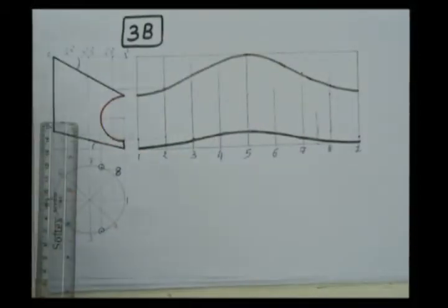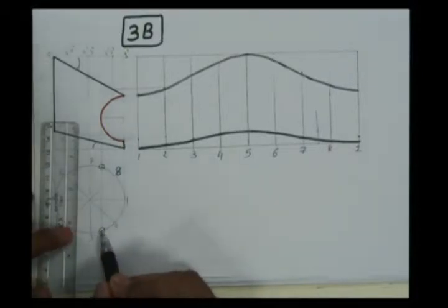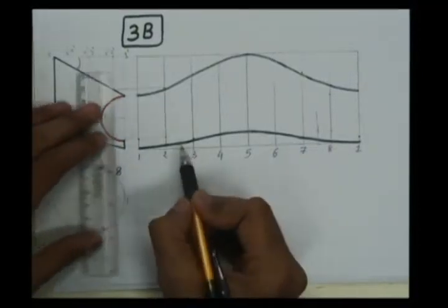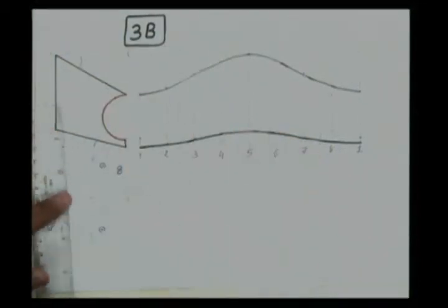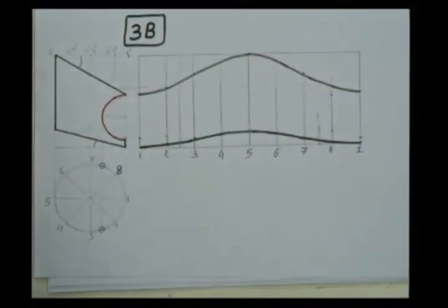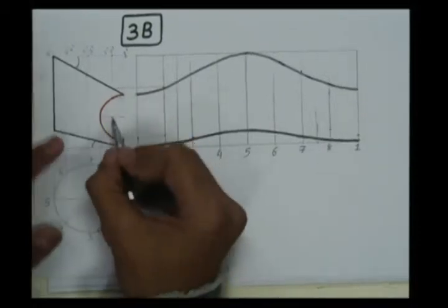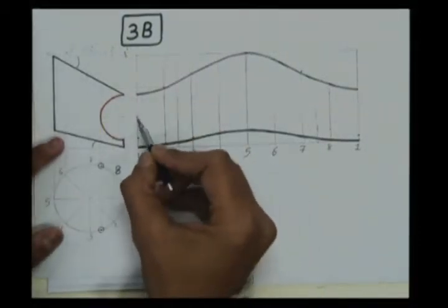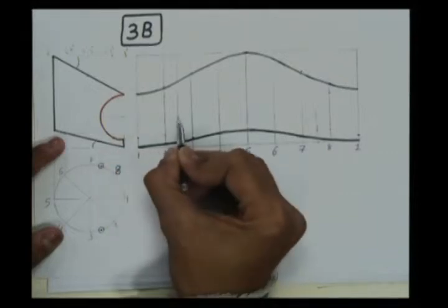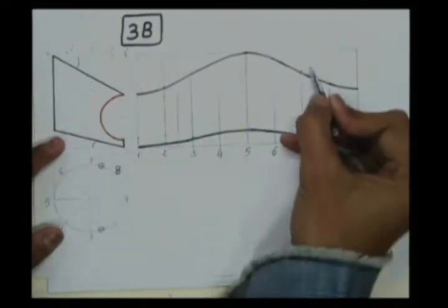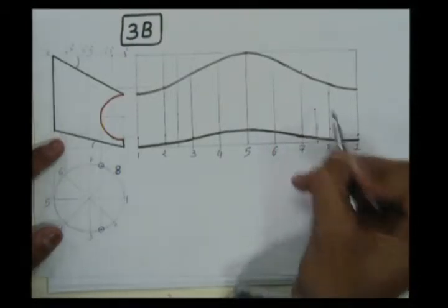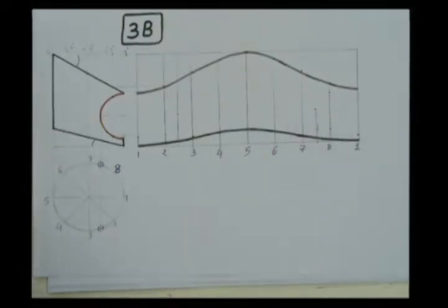Similarly from point 2, between 2 and 3, towards 3 the point is there. So towards 3 you can draw a straight vertical line, or one more imaginary generator over the outer periphery of the cylinder. Now transfer this point to this vertical drawn line. So from here draw a straight horizontal line that will cut this imaginary line over here. Similarly this imaginary line over here. So we have picked up those 3 points also.